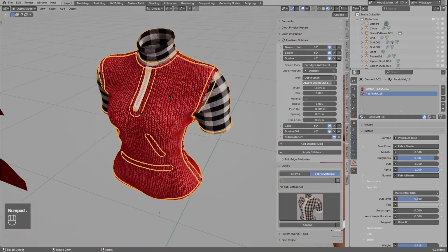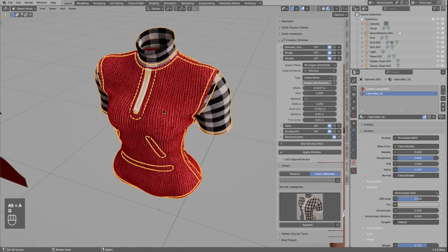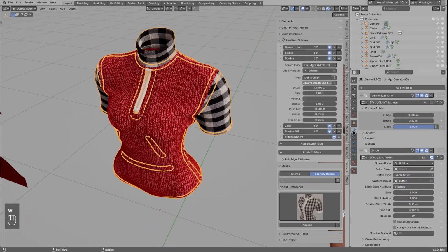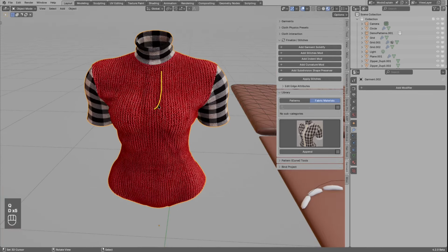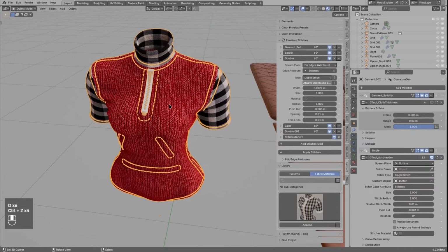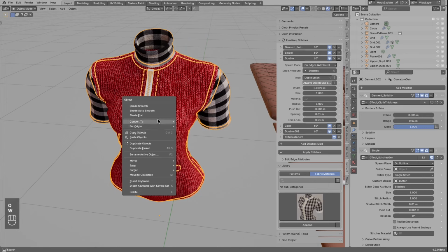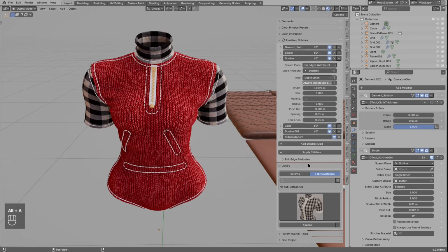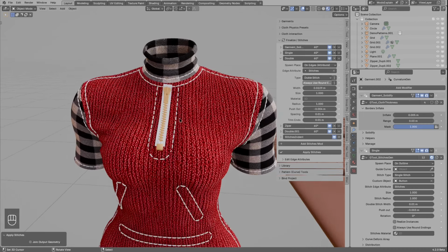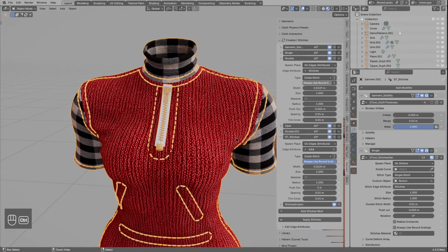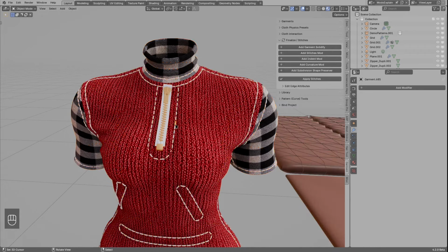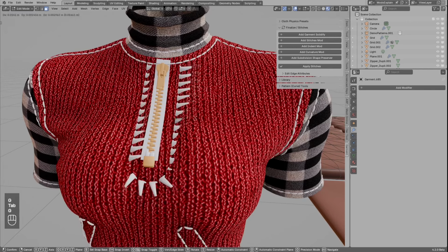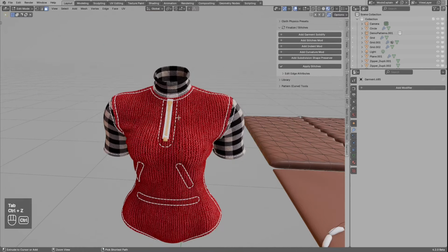And then you can try to export the mesh. Now, if you use Blender apply modifiers, it won't give you a good result. It will remove the stitches. Also, if you try to use convert to mesh, also it will remove the stitches. So I created this apply stitches. This will correctly, one more second, apply stitches, and then those stitches are baked into instances that could be exported or manually edited.